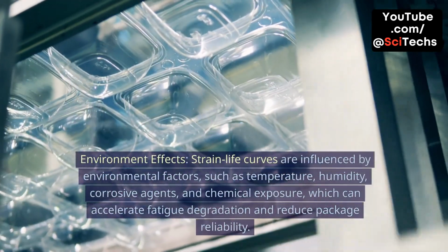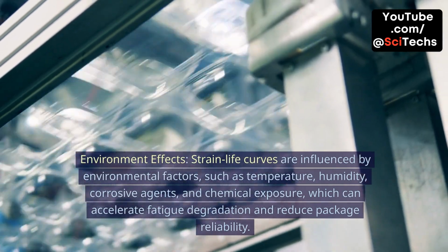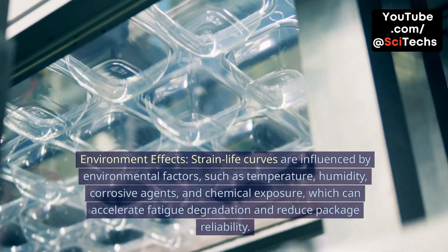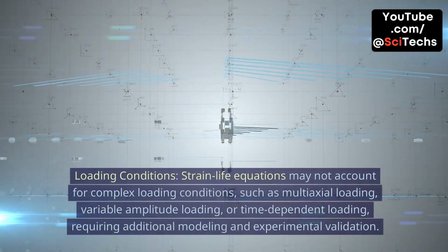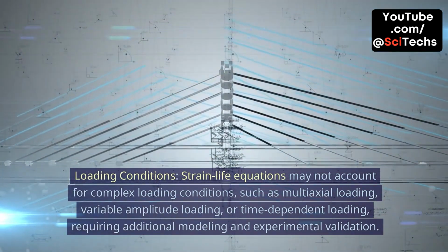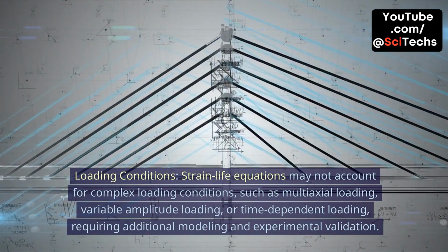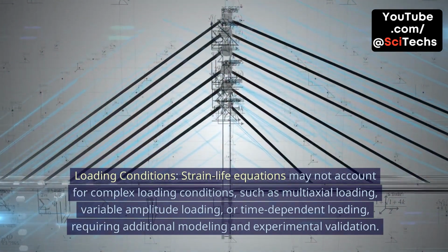Environment effects. Strain life curves are influenced by environmental factors, such as temperature, humidity, corrosive agents, and chemical exposure, which can accelerate fatigue degradation and reduce package reliability. Loading conditions. Strain life equations may not account for complex loading conditions, such as multi-axial loading, variable amplitude loading, or time-dependent loading, requiring additional modeling and experimental validation.